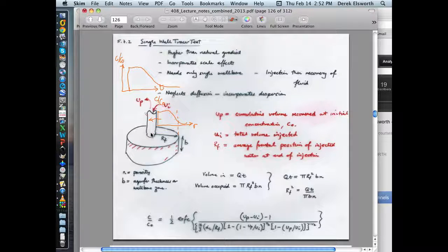And again, the main limitation of doing that is that the dispersion, it won't measure diffusion, because you'd never be able to pump anything into a low permeability material to be able to do a test if this was a clay, for instance. So it would only work in sandy aquifers or silty, sandy, gravelly aquifers. And the magnitude of this dispersion coefficient you get is not really representative of the behavior, because it's a function of the scale of the measurement that we've kind of alluded to. So this doesn't work for you either.